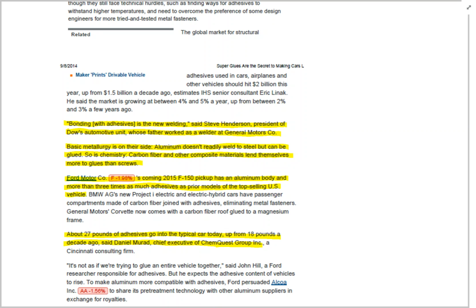So the way you prevent that is you create an electrical isolation between the two members, between the aluminum and the steel. What better way to do that than with adhesives, right? Any other method, I'm going to have to insert another part. If I'm going to bolt the bed to the frame, which I think they still do in parts, but they use a lot of adhesives as they're putting things together as well. You can create an automatic barrier, if you will, from galvanic corrosion.